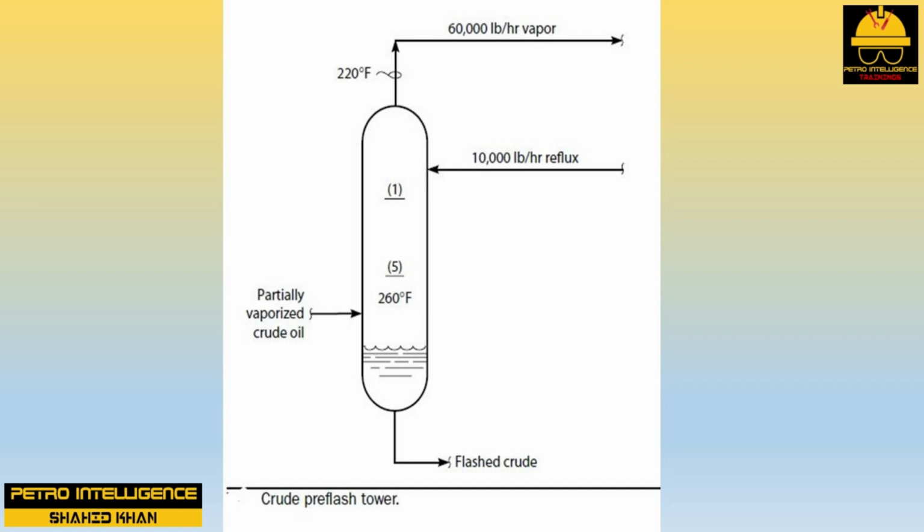We say that the lower trays in the absorption section of such a tower are drying out. The separation efficiency of trays operating with extremely low liquid flows over their weirs will be very low. This problem is commonly encountered for towers with low reflux ratios and a multi-component overhead product composition.